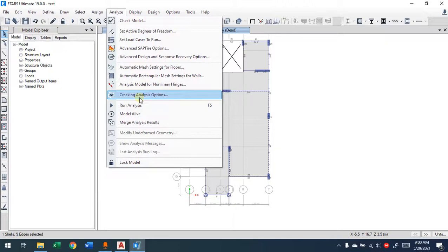If you don't want cracks to happen, or if you want to design the building in a case that cracking is very important, that crack is not allowed, especially in water-related structures, you can go and specify this cracking option. Some codes say that for the slab, provide this section modifier in order to meet the cracking criteria.